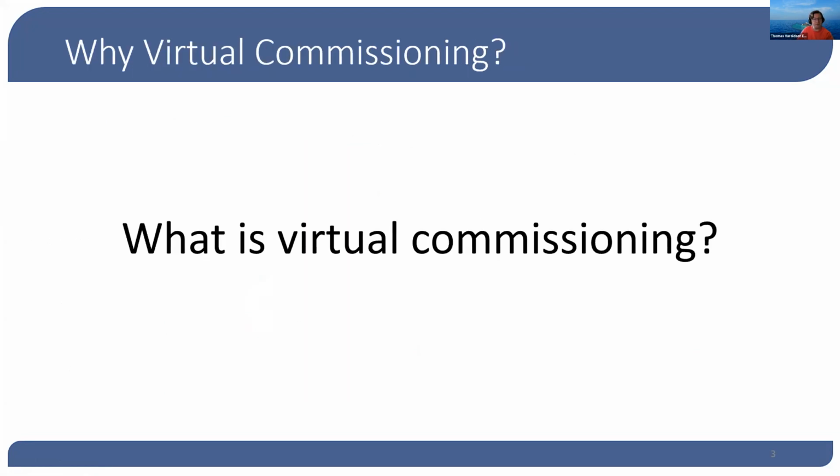So let's start by defining virtual commissioning. I like to think of it as something that's concerned with testing integration of software components. And then we typically mean some kind of control system connected to a simulator, providing some kind of input. The control system can run either natively on production hardware or in some kind of virtual environment, which is similar to what we know as either software-in-the-loop or hardware-in-the-loop testing.